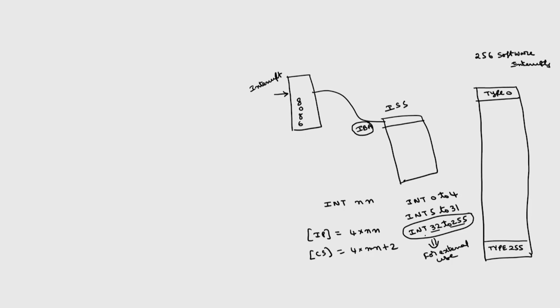For example, if I use INT 32 type of interrupt for IR0, say I want IR0 to operate as type 32, what are the corresponding addresses? 32 into 4 is 128 in decimal. For hexadecimal, 16 sixes are 96, 16 sevens are 112, 16 eights are 128, with 0 remainder, so 8 and 0, that is 80H.